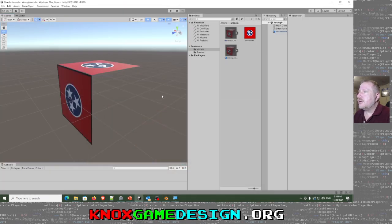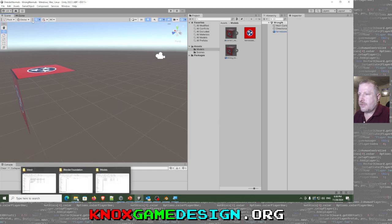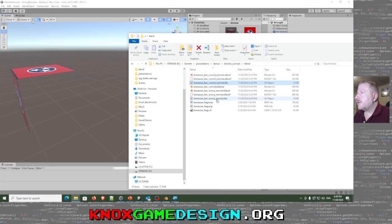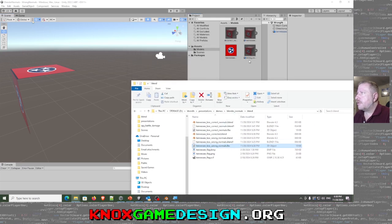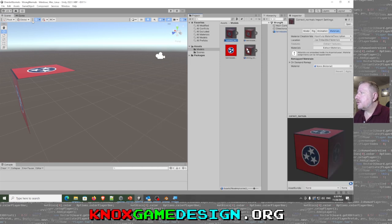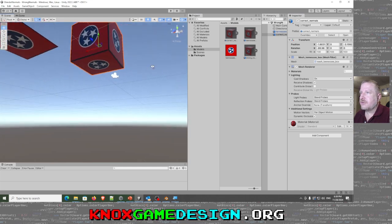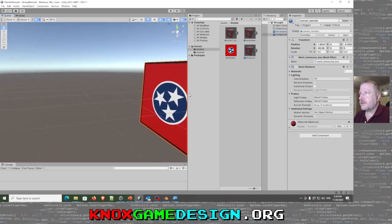And then in Unity, I'm going to come over right here and find my file, which is corrected normals.fbx right there. So I'm going to pull that into my models right there. So here's corrected normals. You can see in the little preview right here, it's got all the normals corrected. Then if I just pull in corrected normals, then it should be right. So this was the same box with the problem, but I flipped that one and then it fixed it.